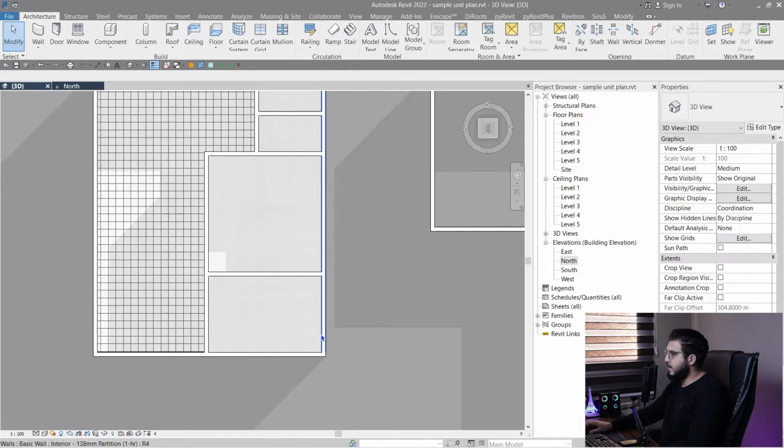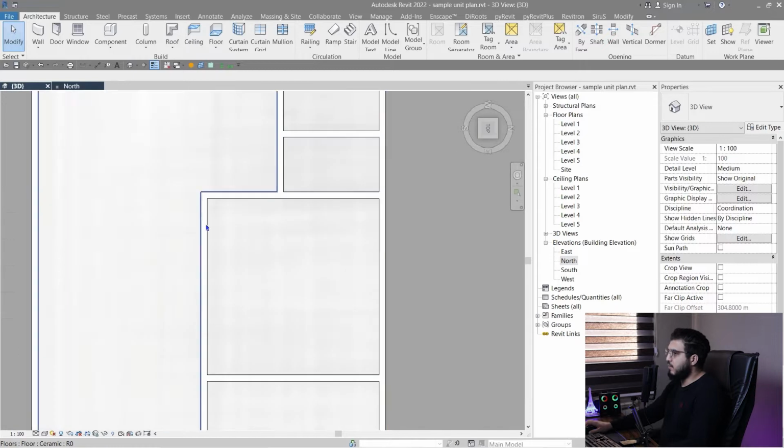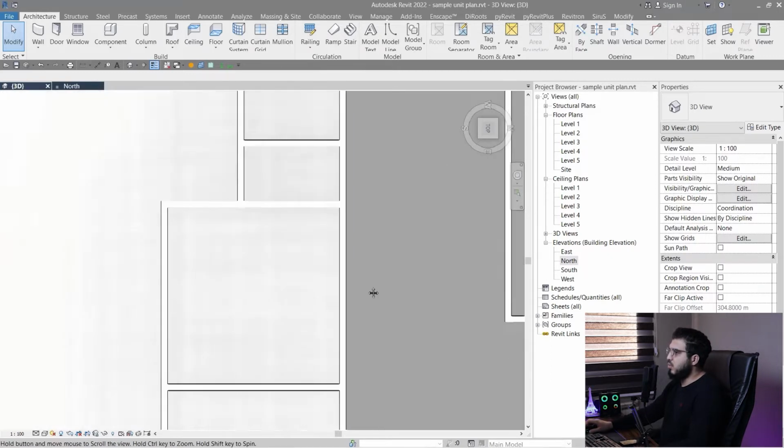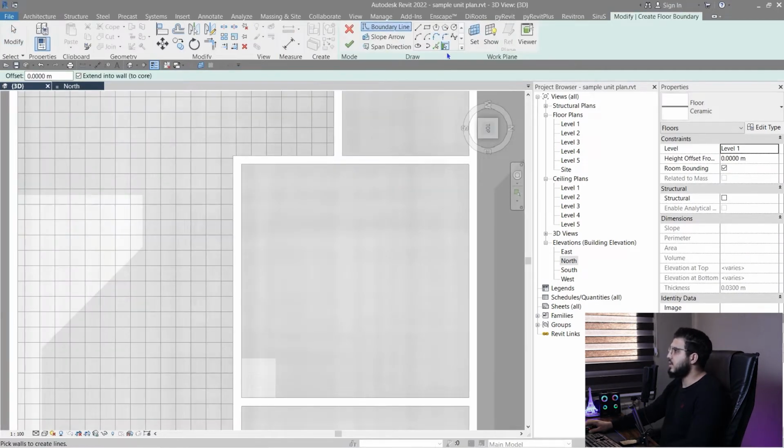But sometimes there is a tip that I'm going to show you in here, and that is the finished floors in, for example, a bathroom, where you want to place an item for sloping, for example, to gather the water. So to do it, you need to create another floor in here, and this time let's use pick lines again. In here, let's assign a 3 centimeter offset.